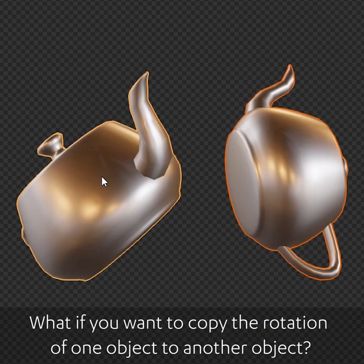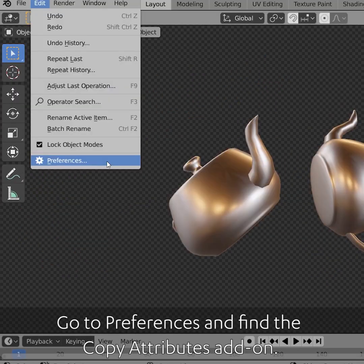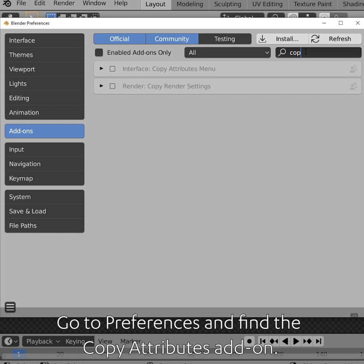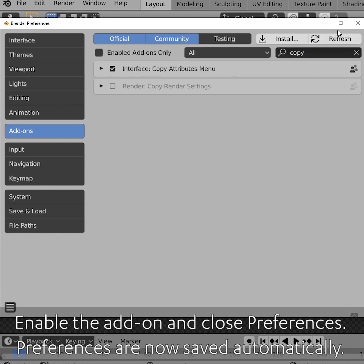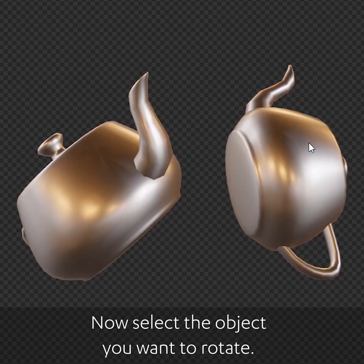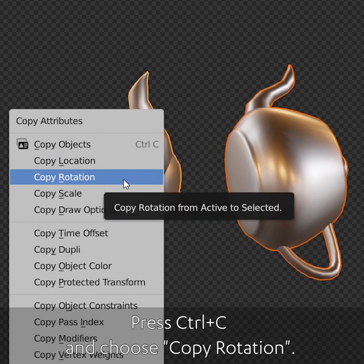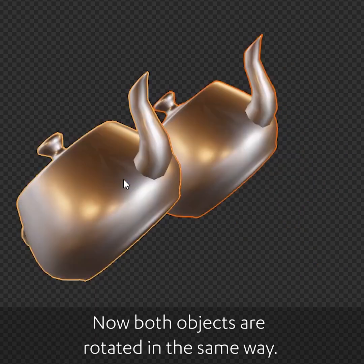What if you want to copy the rotation of one object to another object? Go to Preferences and find the Copy Attributes add-on. Enable the add-on and close Preferences. Now select the object that you want to rotate, then select the object from which you want to copy the rotation. Press Ctrl C and choose Copy Rotation. Now both objects are rotated in the same way.